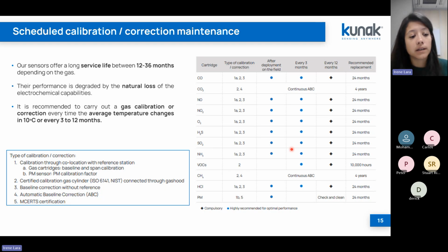Next week you can start using the tool, select the time period in which you introduced the gas, and also rebuild the data for all that week between the time you introduced the gas and you performed the calibration. In that case, rebuilding the data will be quite useful as well.